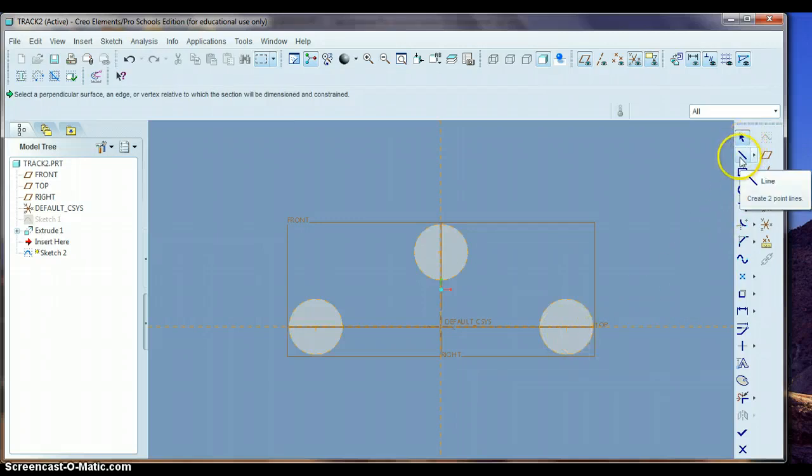Go to the line, which is the second one down, and there's a little arrow right beside the line that we can change. We used it last week. The second one here has these little circles beside it. If you hover your mouse over it, it says line tangent, and we'll click on that button. So the line tangent one, the second one from the left.